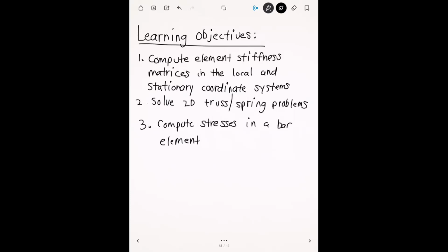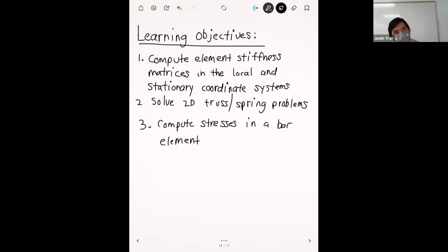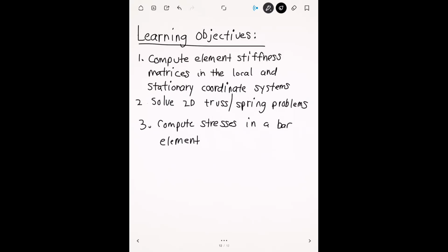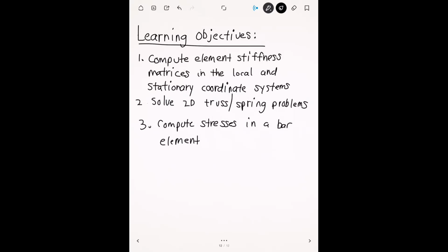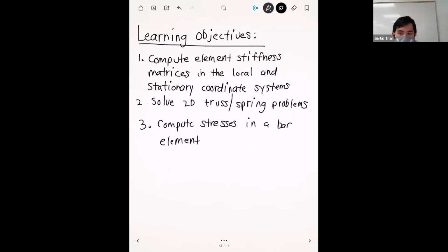For like the truss and the road, where they meet? You should still be able to mesh it even if there's a gap. Do all the parts of your geometry have the green check mark next to them? Yeah. Okay. Let me just double check, because there is one rogue part that you have to suppress, and that might be preventing it from meshing.